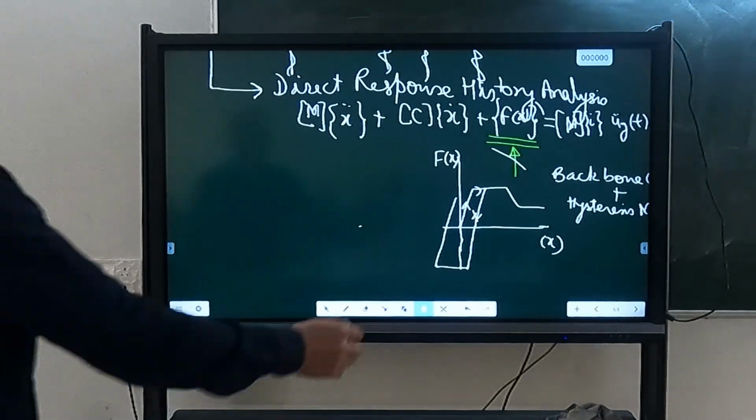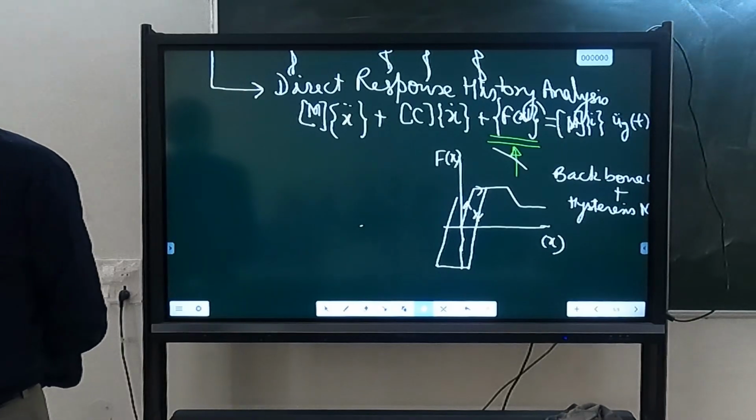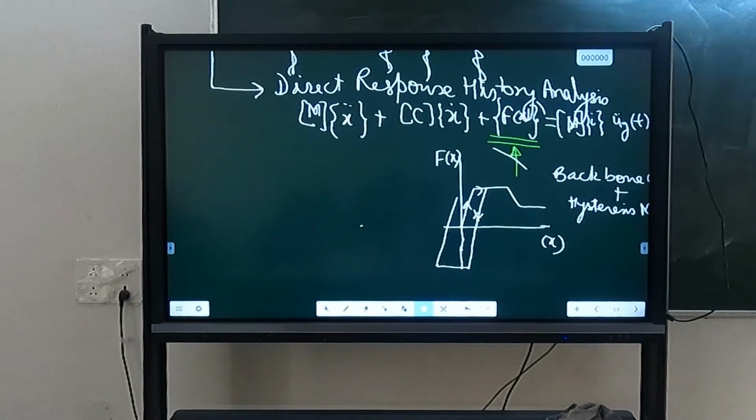That's what we are doing here, in this equation. We make a model. When I said nonlinear model, what does that mean? Each member was replaced by an elastic component and member plasticity. So where has that come from? From tests only.